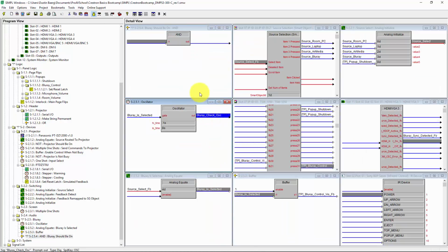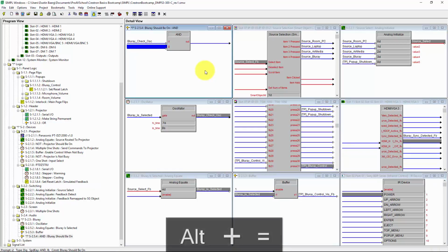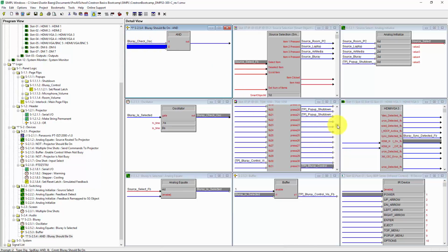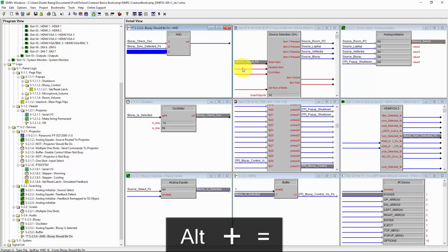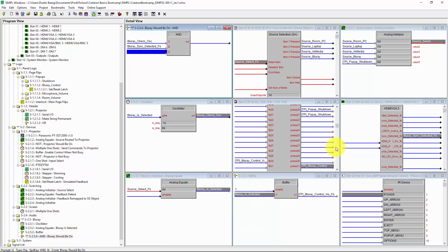These will both work the same, or have the same comparison. Comparison is not the right word. We're matching with the same signal. So if it's on and if it should be on, let me rephrase that. We're actually checking a couple things. So if oscillator pulses and sync is detected, and actually sync is not detected, that's what I need. So I need a not in there. No sync.